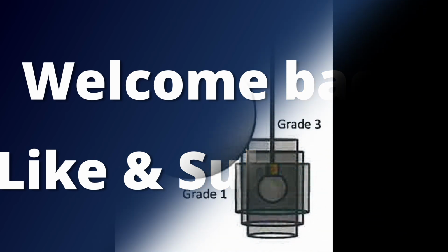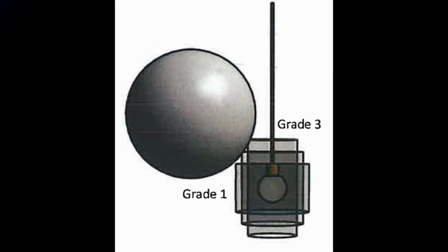When people talk about BIM, they talk about 3D models, but BIM is not about how detailed a component looks. It's about how efficiently information is structured, managed, and reused throughout a project. In this module, we're going to look at model development methodology, how Revit models should grow over time, how much detail is appropriate at each stage, and why less geometry almost always creates better BIM. The purpose here is to explain why certain modeling approaches are better than others and how those decisions affect performance, coordination, and long-term usability of the model.